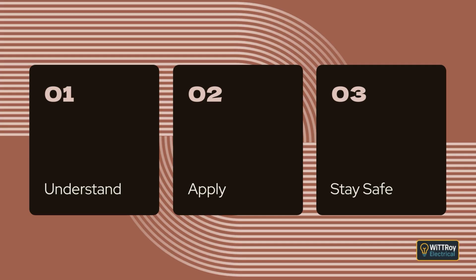Clause 3.7.2.3.4 Mechanical connection devices. This clause explains the requirements for mechanical devices used for connecting conductors. These devices must comply with an appropriate standard, must not rely on compressing the insulation to make an electrical connection, and must carry fault current safely.